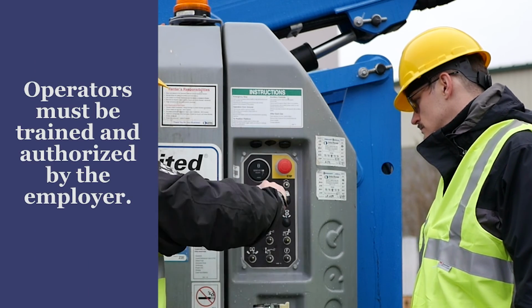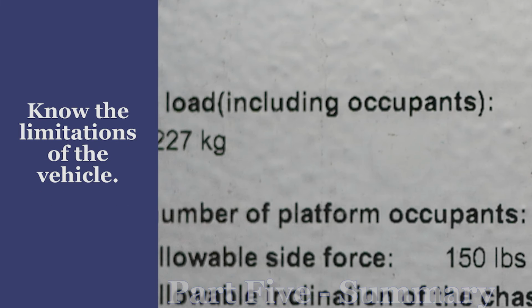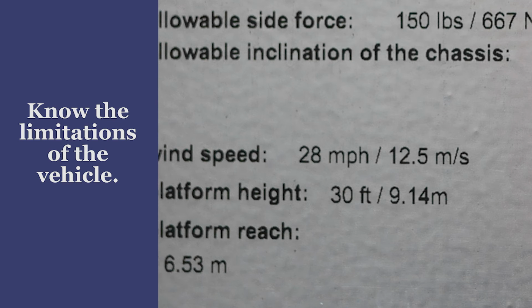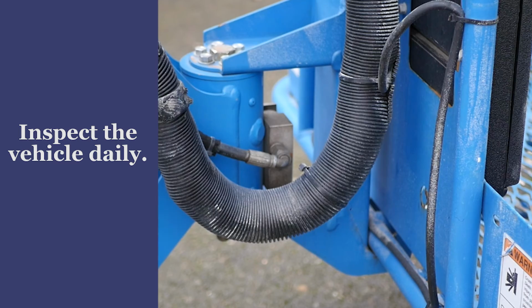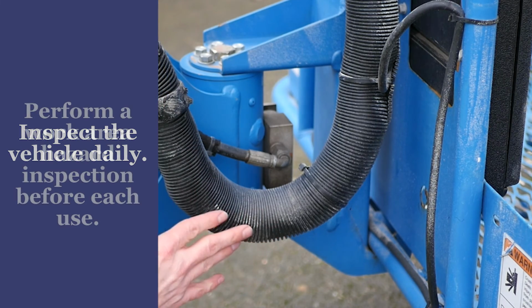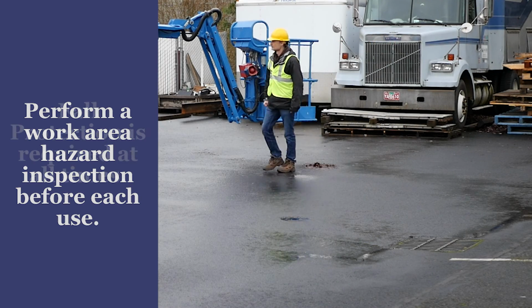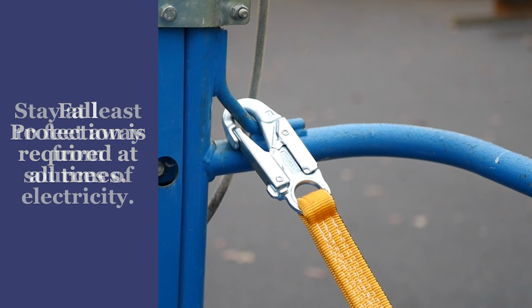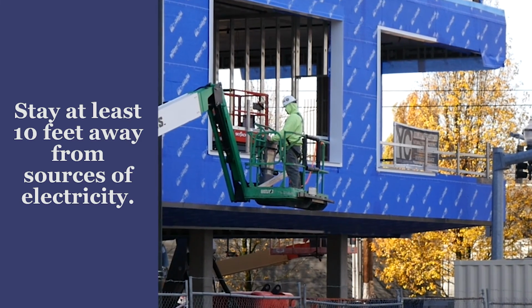Aerial lift operators must be trained and authorized by the employer. Know the weight capacity, maximum slope, and maximum wind speed for the aerial lift you are operating. Complete an equipment inspection each day before use. Survey the work area for hazards before each use. Connect to an approved fall protection anchor point. Maintain a distance of at least 10 feet from electrical conductors.